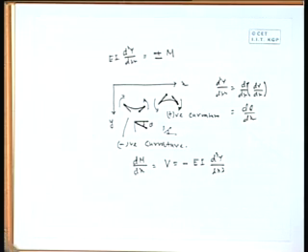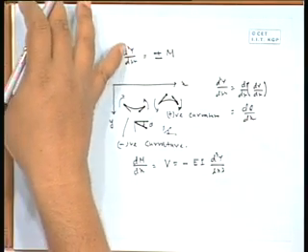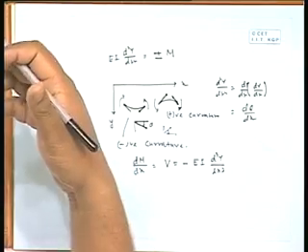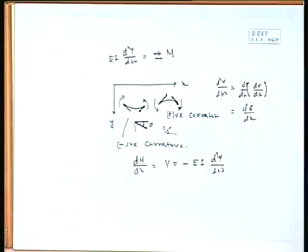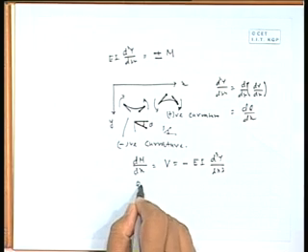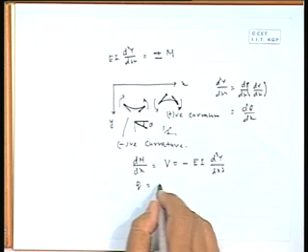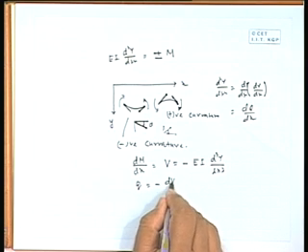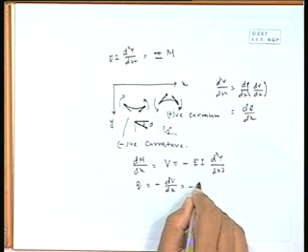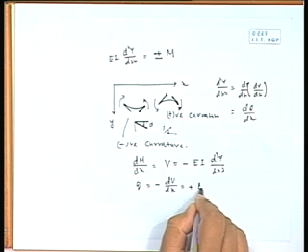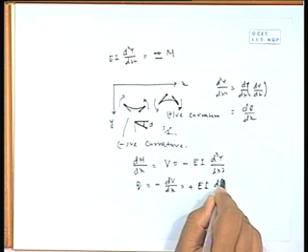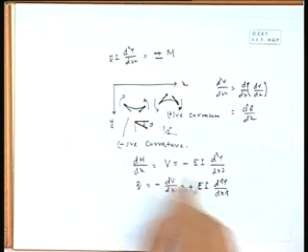What is moment? Moment is minus EI d2y by dx square. So, for the derivative of that, the minus sign we have to incorporate. Okay. And the last term is the loading q, equal to minus dV by dx, or it will be plus EI d4y dx to the power 4.